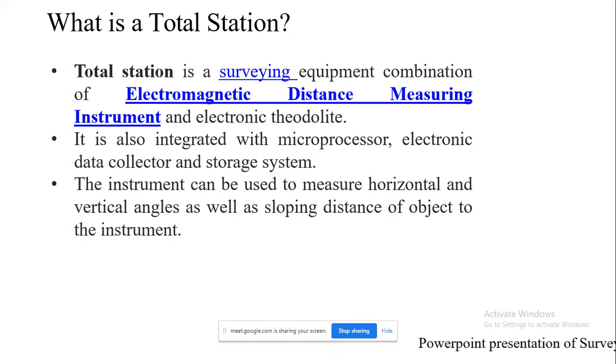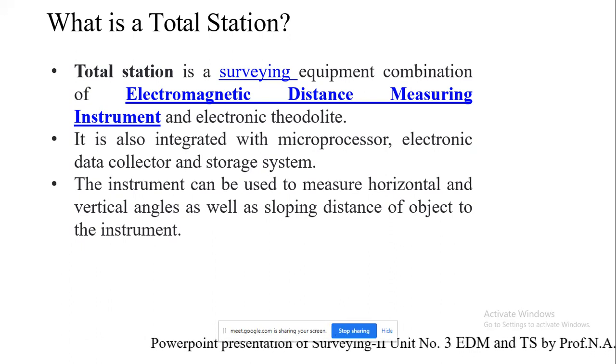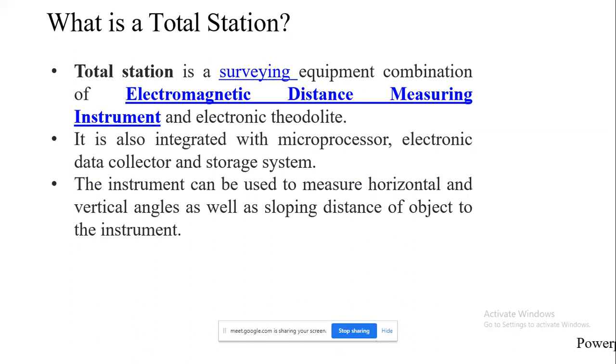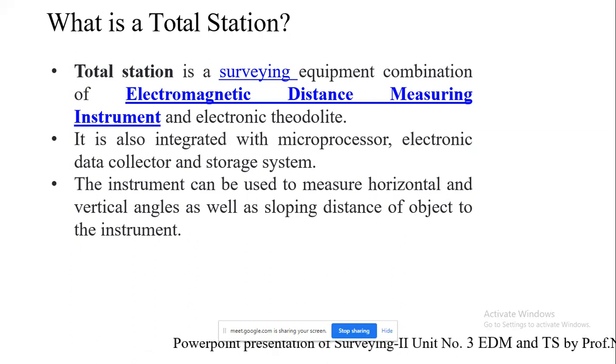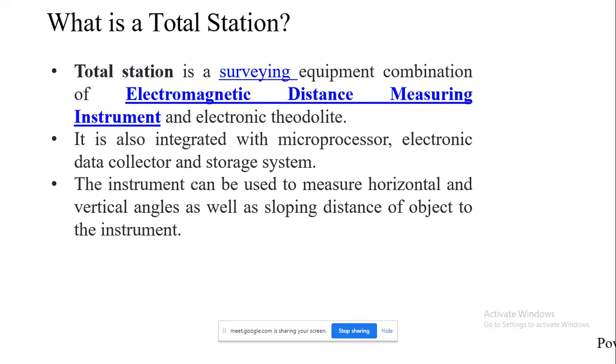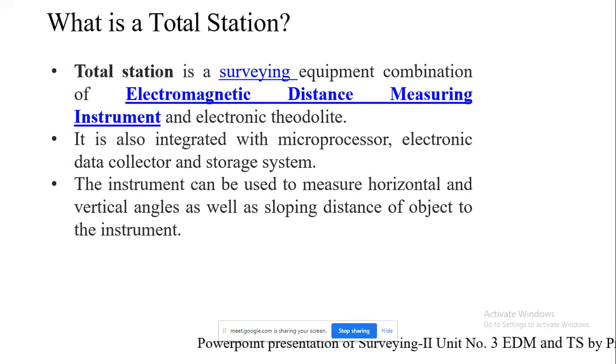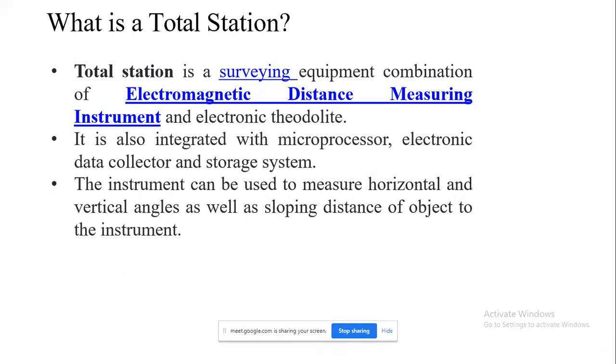It is a combination of all that. We can measure horizontal distance, horizontal angle, vertical distance, vertical angle, and if you are unable to bisect perfectly horizontally, that is to the ground level, it gives the sloping distance also. So you can calculate the slope with respect to your station up to the point which you require. Along with the horizontal distance, it gives us the sloping distance.